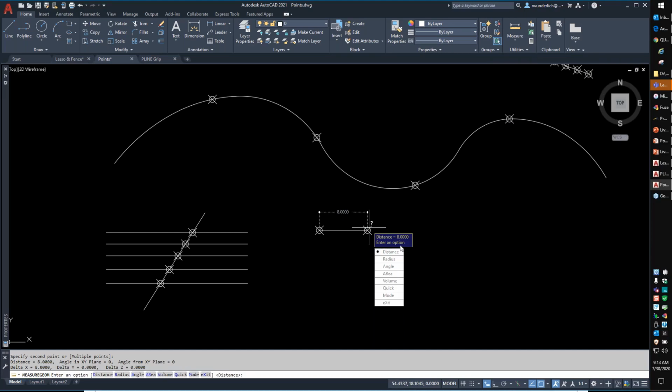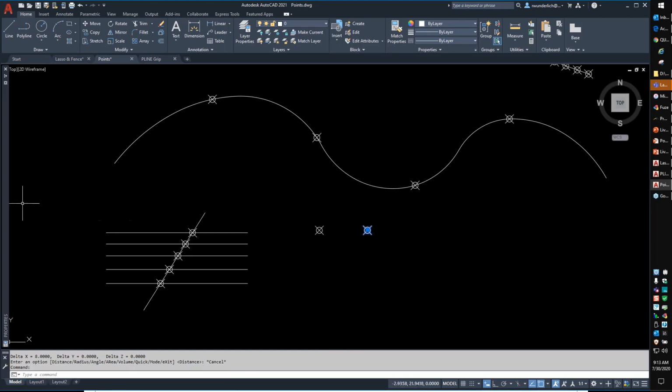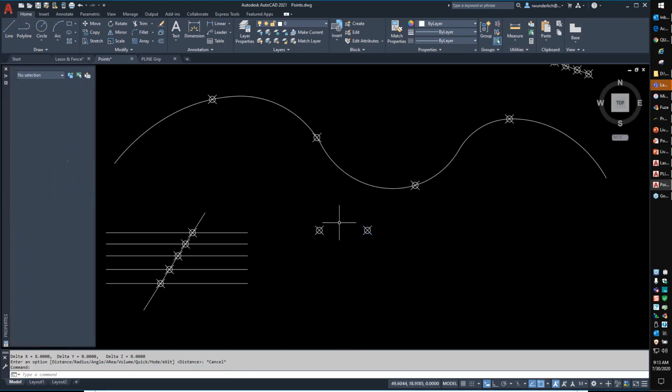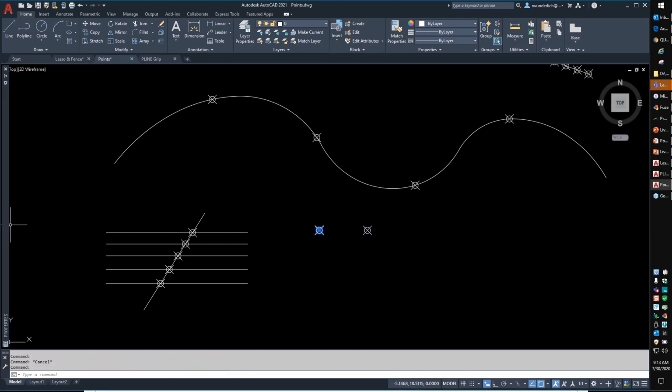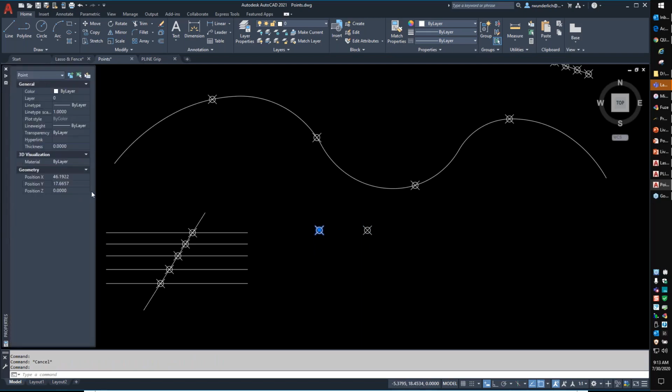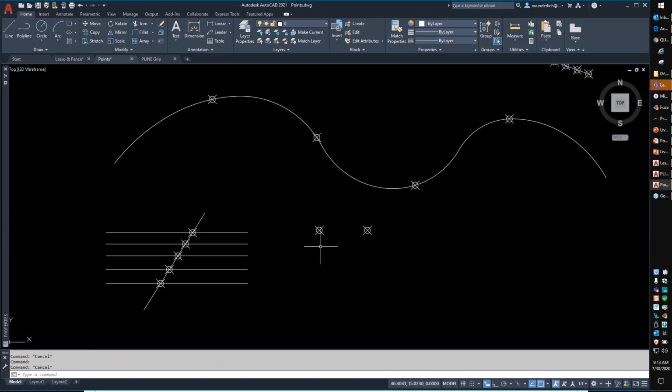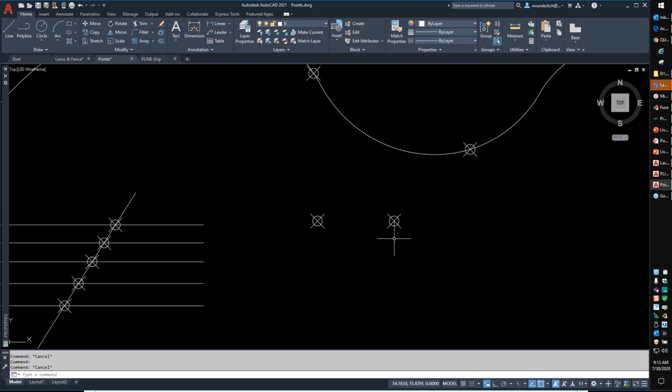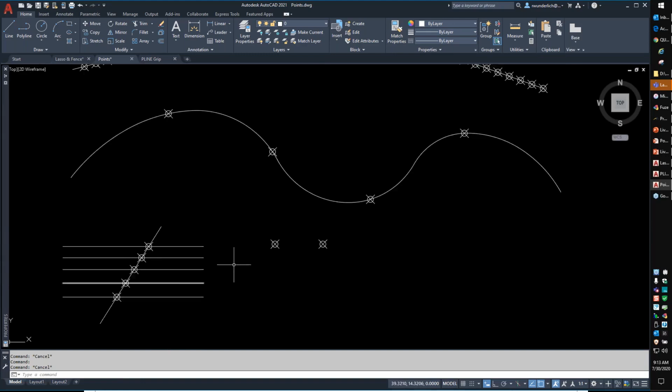So they are 8 units across in the XY direction, and it's 11.3137 units in the X, Y, and Z direction, because this point here is at an elevation of 8, where this point is at an elevation of 0. So if you know that your linear distance from here to here should be something and it's not the correct distance when you measure, double check and see if you have 2 different Z elevations. And if that's a problem, make sure you set OSNAP Z to 1.